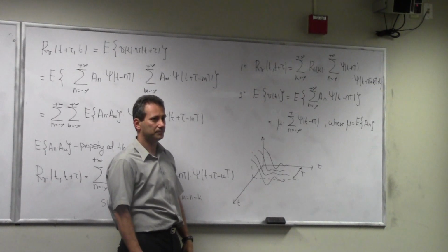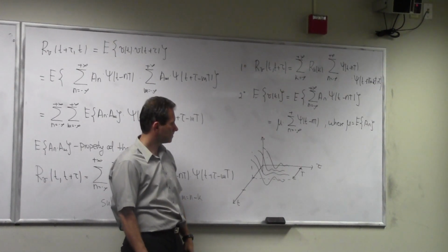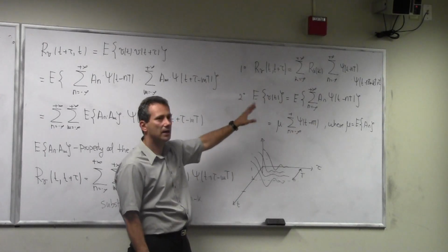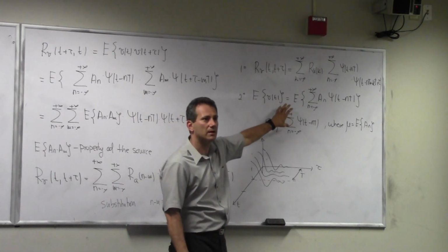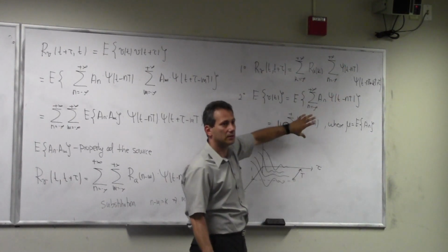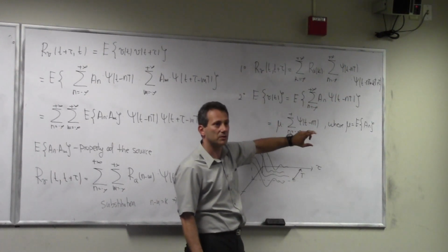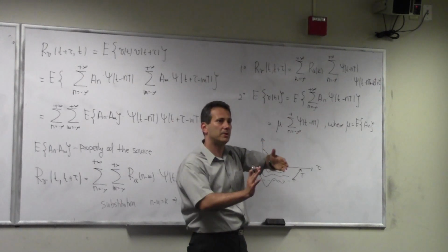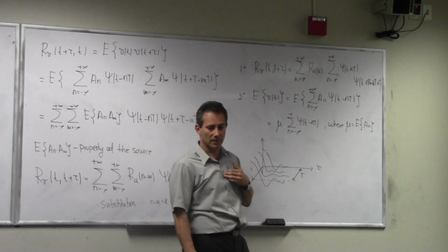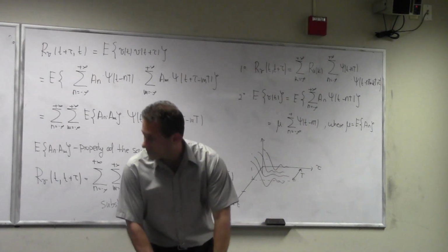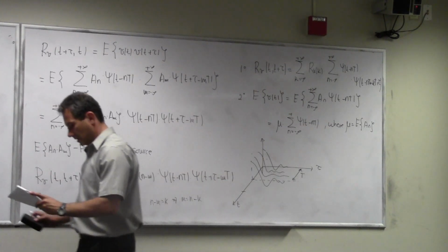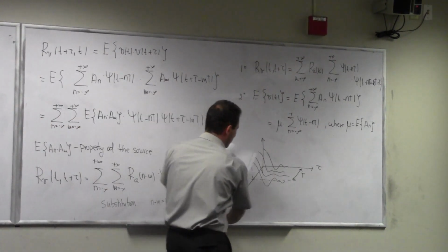But in this case, you need to have n not equal to m. We're past n and m. We needed n and m just to establish that this is periodic. Now that I know it's periodic, it's a cyclostationary process. Let me average over one period so that I can get its power spectral density. So let's do exactly what I just said, following the same approach.